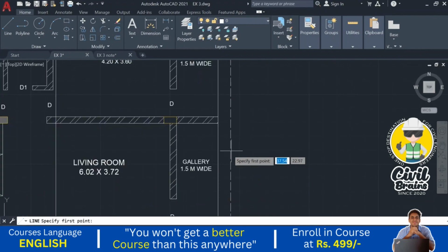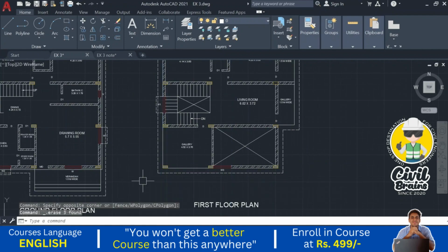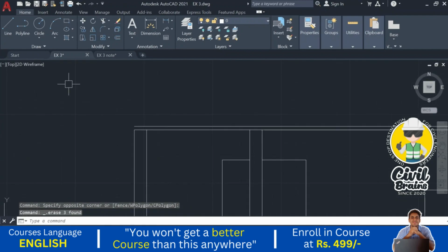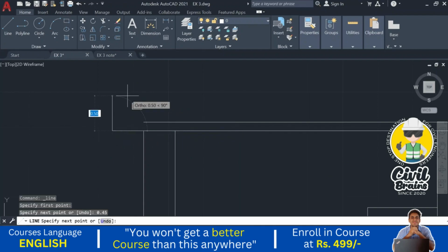So here you can see this one. After the gallery, the slab projection is 0.45 and here it is 0.45. I just delete whichever is not required. I project the slab here, 0.45, thickness is 0.125, and this one 0.45. Press enter.